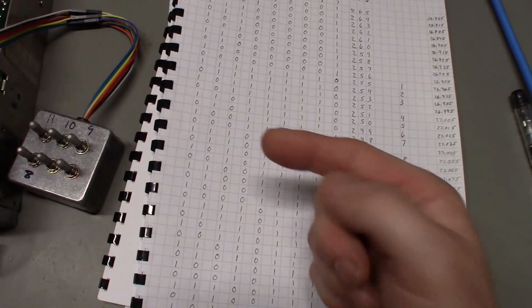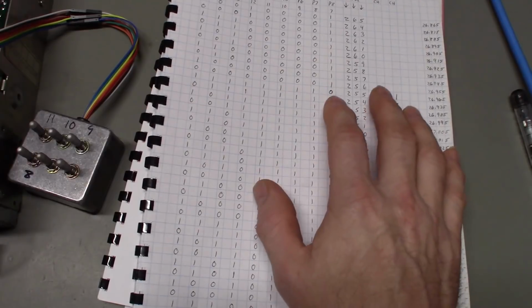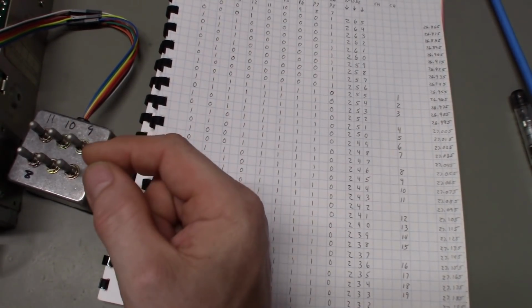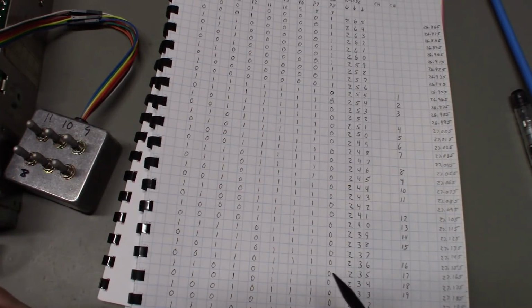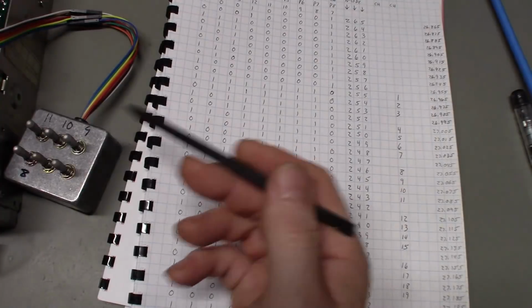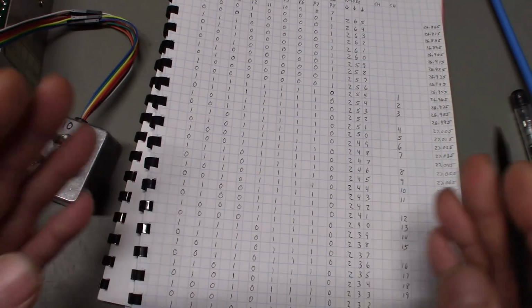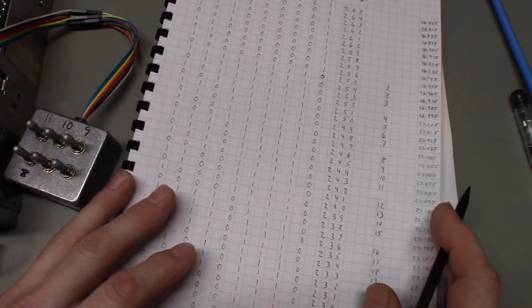And that's another thing to remember. A radio like this is never going to be able to cover 511 possibilities of that PLL. Just because with the PLL you can flip some switches and get 511 different combinations doesn't mean your radio is going to get that. You're never going to get it to cover 5.11 megahertz worth of band spread. It just ain't going to happen.